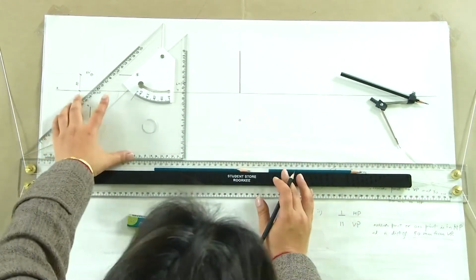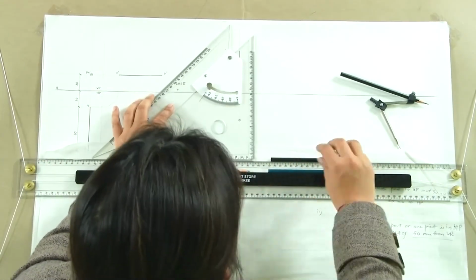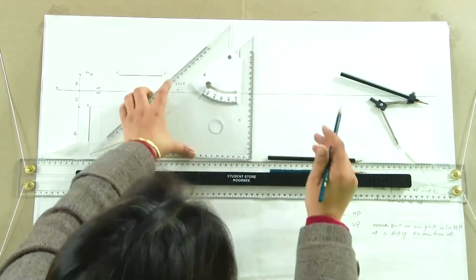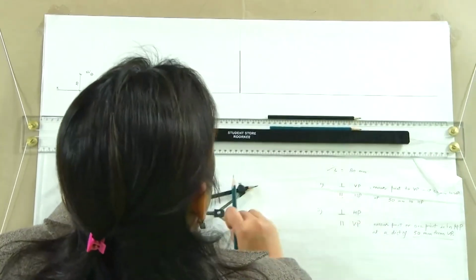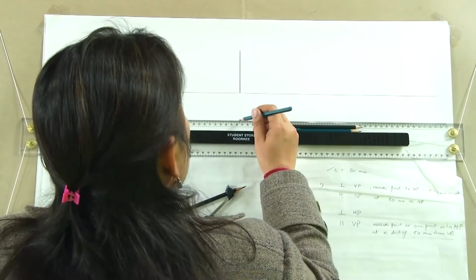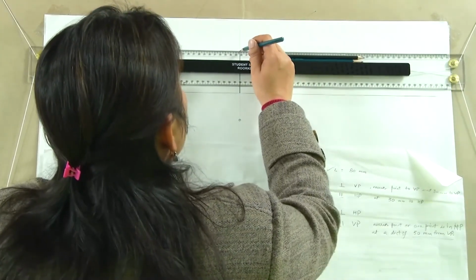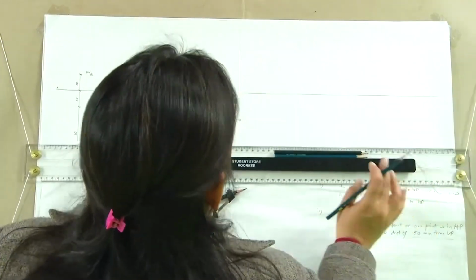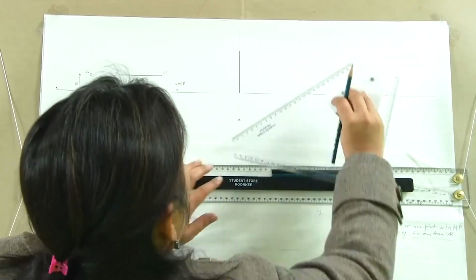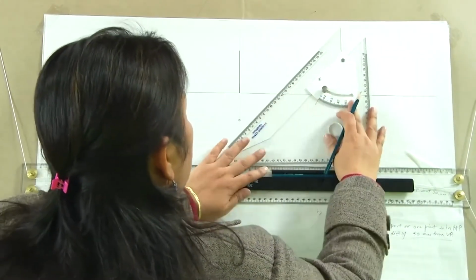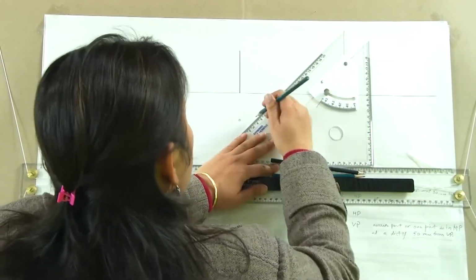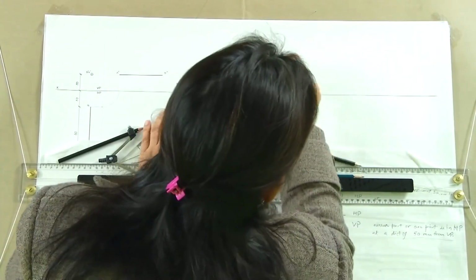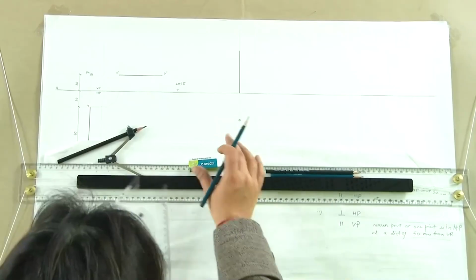And now, if we have to draw the side elevation of it, again we will do the same thing. We will take the projections up to the side screen first. We will take the projections from the plan into the elevation and project it to get the elevation of the projections of both the points.